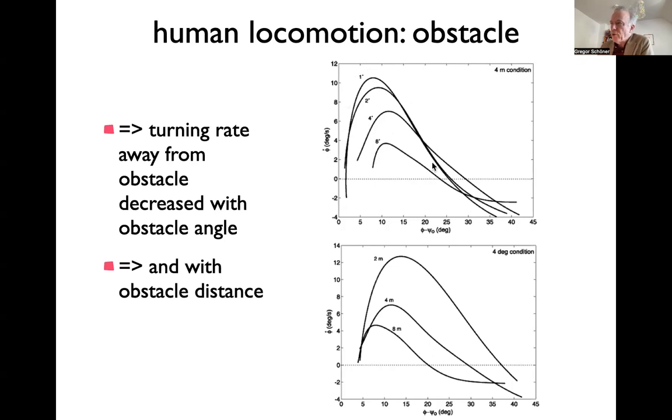Again, ideally, these curves should lie on top of each other, or at least be aligned. And that would not be the case in that you have some transient to actually get onto that. And you see, they actually convert you to an attractor, right? This is actually an attractor in a sense. It's, again, complicated by the fact that under different conditions, you shift this by a different amount, which would be that attractor on the outside, because you also have a target to go to. And so this is where the obstacle repulsion and the target work together to build up an attractor.